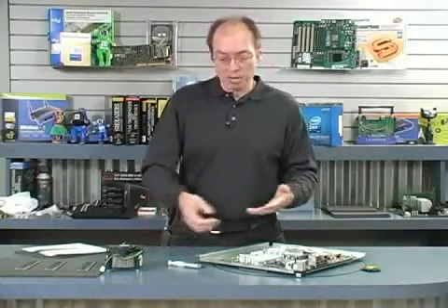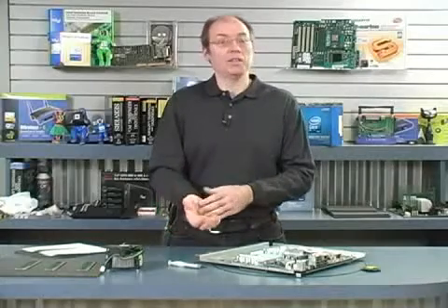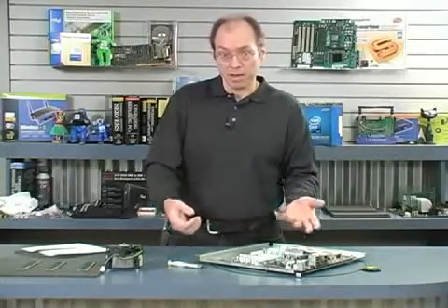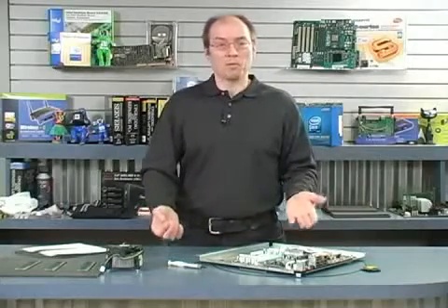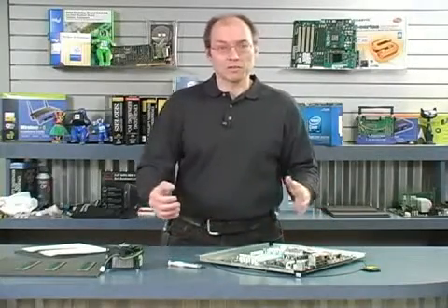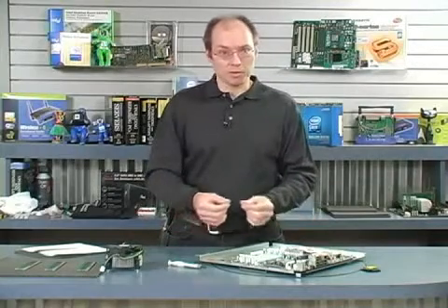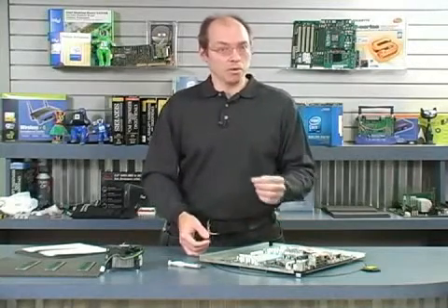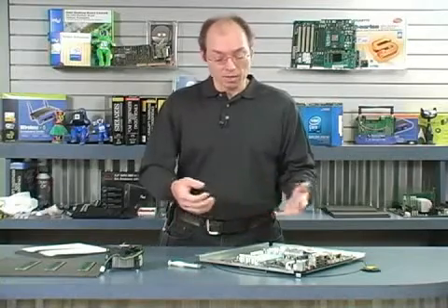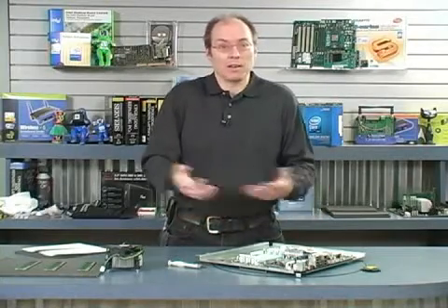Now, I've had people buy processors that come with heatsinks and scrape the phase change material off, never even using it, thinking that the grease is better. Either one performs pretty much the same thermally. In fact, I've seen numerous tests of hundreds of different types of thermal interface material, and rarely see more than a 1 degree difference in the actual operating temperature of the processor, depending upon the different materials. It just doesn't really matter.